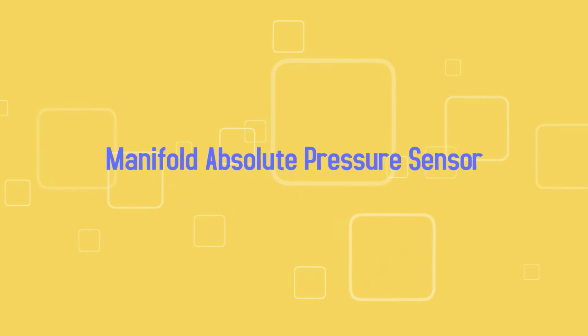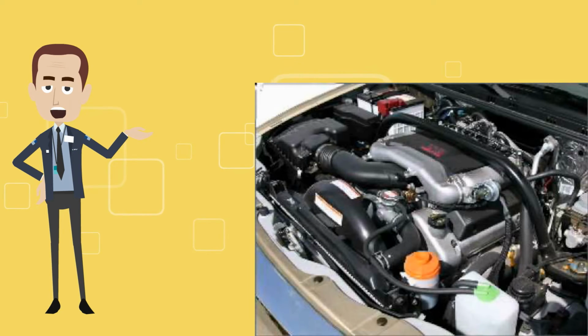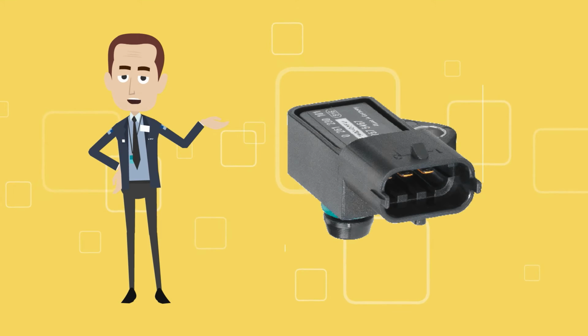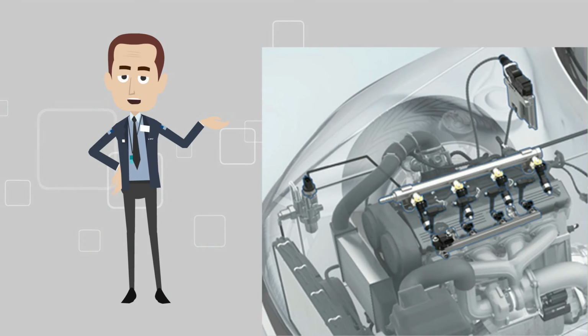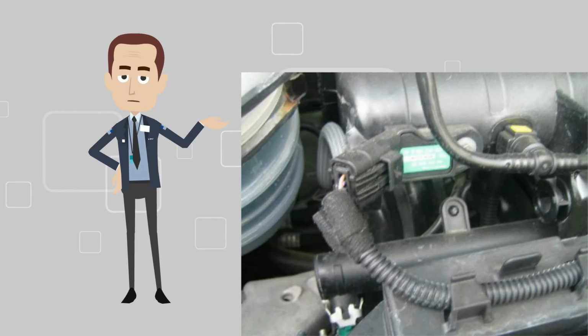Manifold absolute pressure sensor. This sensor is a key sensor because it senses the engine load. This sensor measures air pressure, which tells ECM the current altitude of a vehicle. With the help of this information, ECM can adjust the ignition timing and fuel enhancement. It is bolted on the intake manifold or linked with a vacuum pipe from the intake manifold.